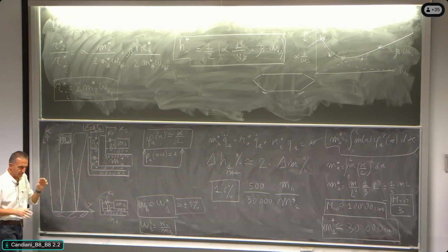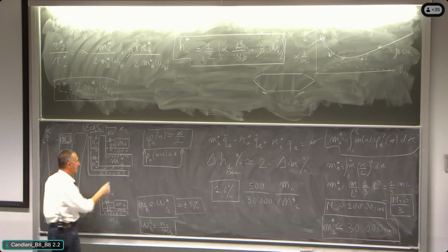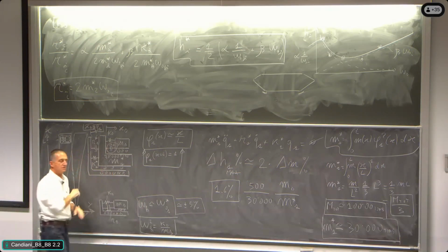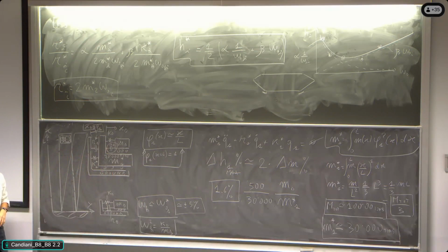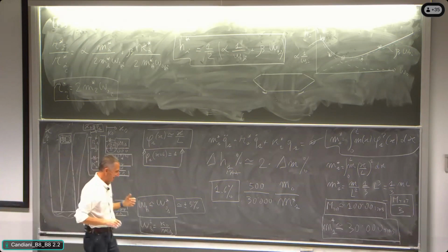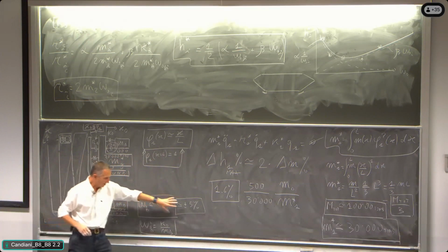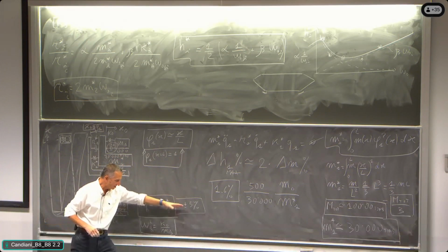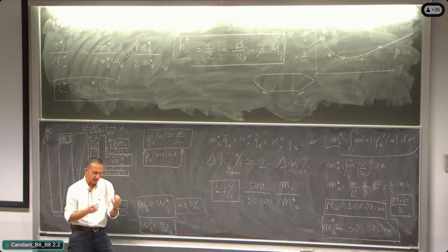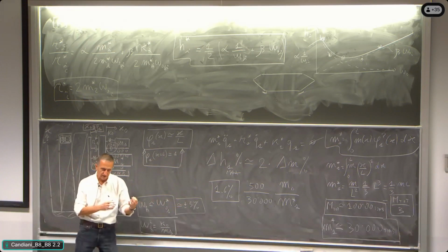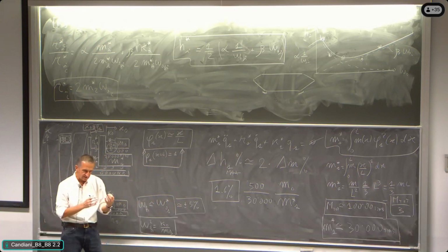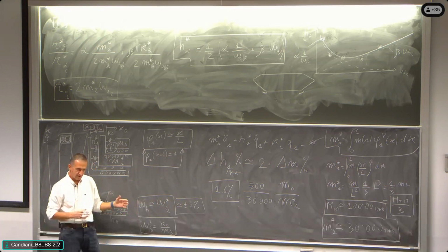and then there is another point that we didn't discuss yet. The value of the damping with which it is connected to the building, all right? So under the hypothesis that there is an optimum tuning, so the natural frequency of the tuned mass damper with respect to ground is in the order of some percent different from the frequency of the mode that we have to tune.